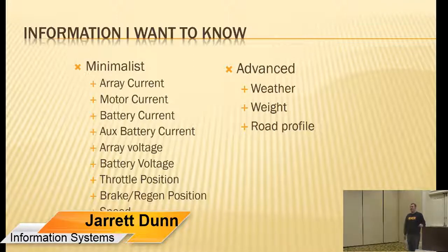And finally, speed, because all these things, how you relate to the speed, your current as it relates to the speed, is important. That's how you know your car. If you have a certain speed, you're drawing 100 amps. If you go up a mile an hour, you might be drawing 200 amps. There are knees in the curve of your current usage. You might want to make sure you're below 1 or above 1 to be efficient.